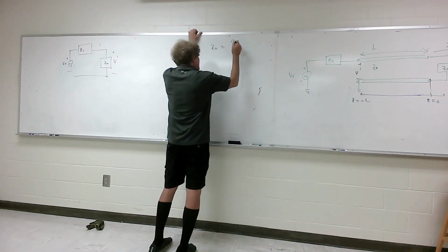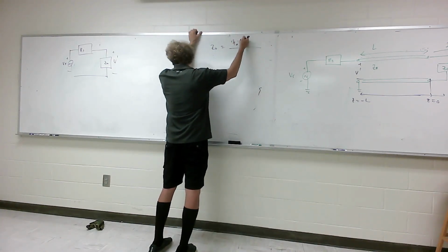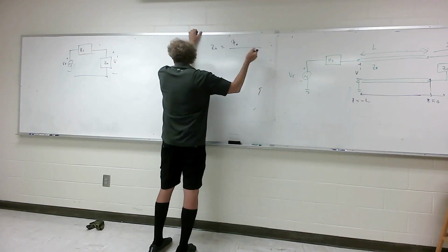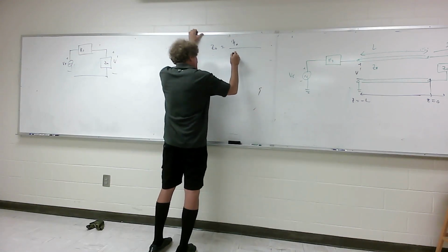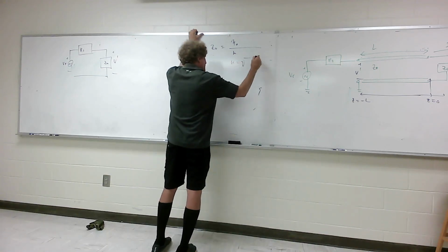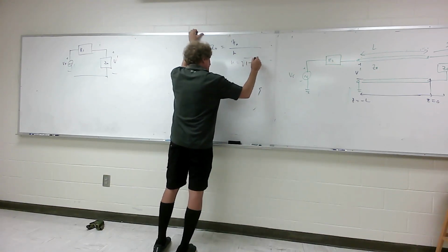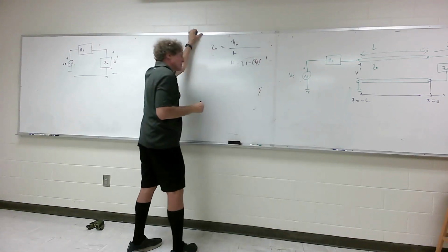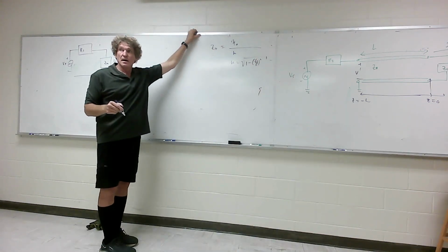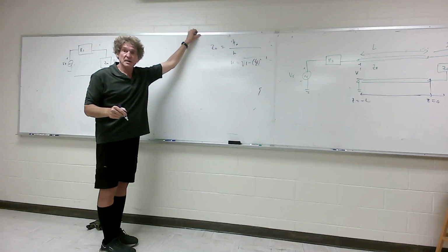Yes. So it's eta naught if it's air-filled, or eta divided by the square root of epsilon relative if it has a material in it. Then it's divided by k. And k, of course, would be the square root of 1 minus the cutoff frequency over the operating frequency, squared. I want to make that clear.